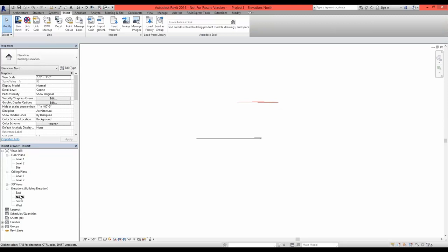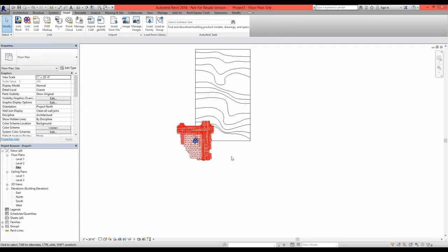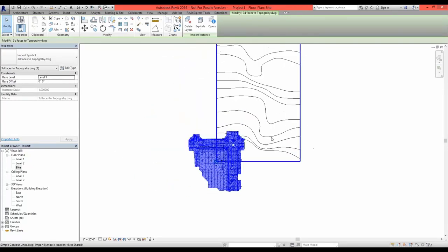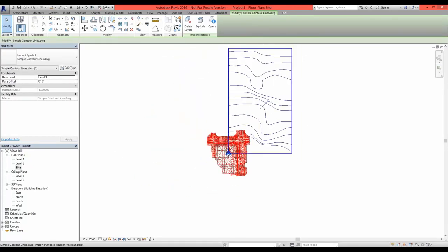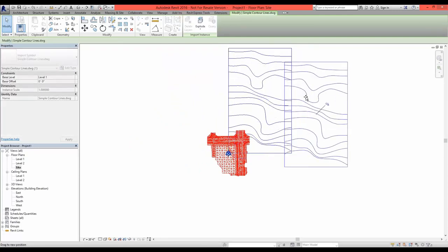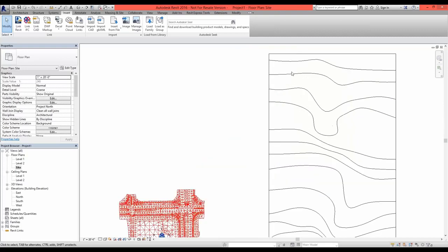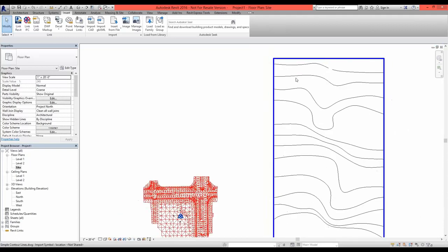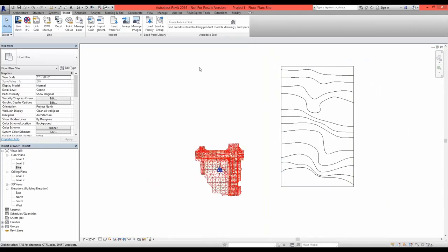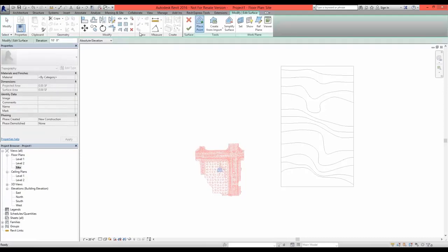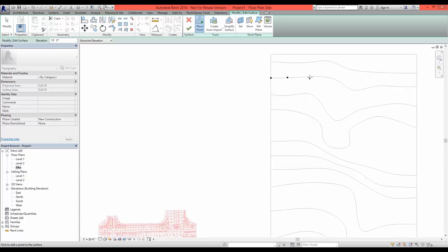And so in this case, civil has already done a lot of that work for us, and we have this site import. And so one thing that we could do is we could utilize this line work, for example, and I'll just move this off to the side, to actually draw out and follow this line work. So this might be the case where we're trying to draw this based on a PDF, and it has actual number values in here to tell us exactly what height that should be. And so in one way, we could go through and select our topography surface, select our height based on the height specified on our plan, and just simply utilize that line work to go ahead and draw out our particular line work.